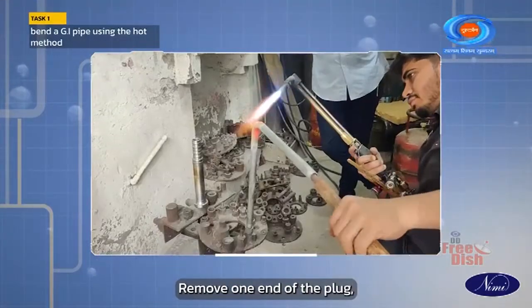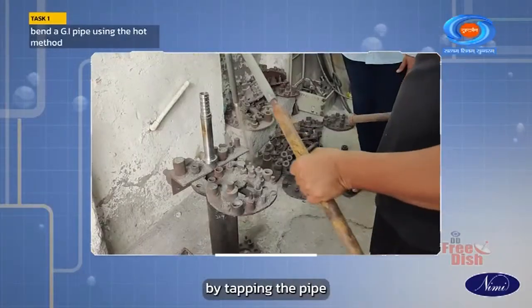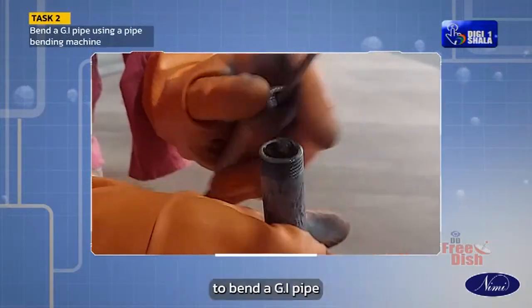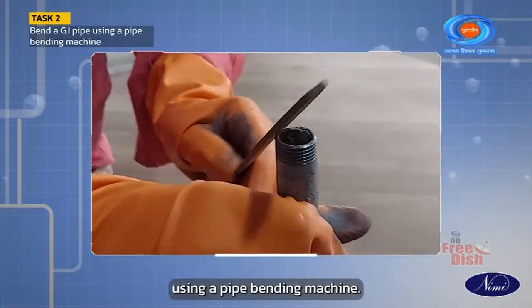Remove one end of the plug. Remove the sand by tapping the pipe gently with a hammer. Now, we will use a cold method to bend a GI pipe using a pipe bending machine.